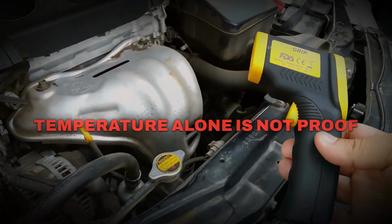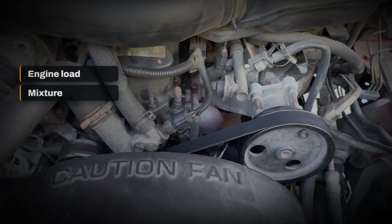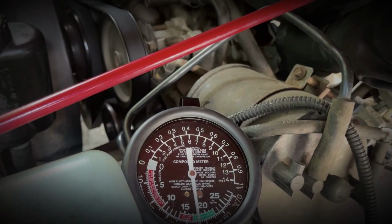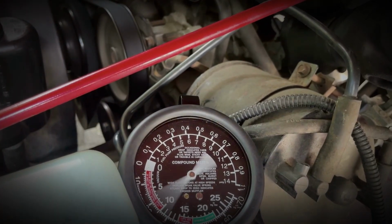Do not use exhaust temperature alone as proof. Temperature changes depend on engine load, mixture, converter location, airflow, and test conditions. A temperature difference may support a diagnosis, but it should not be the only reason a converter is replaced.